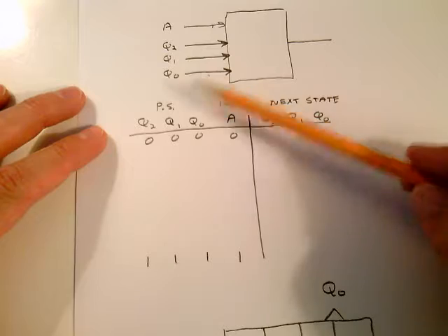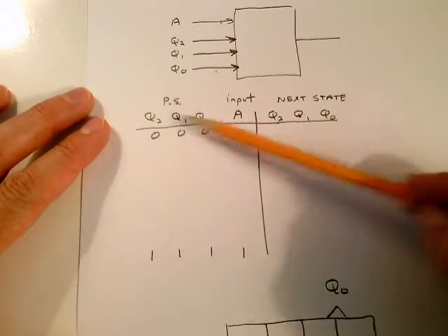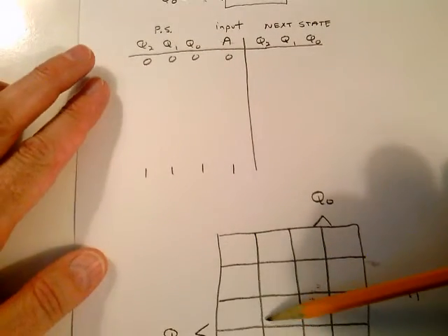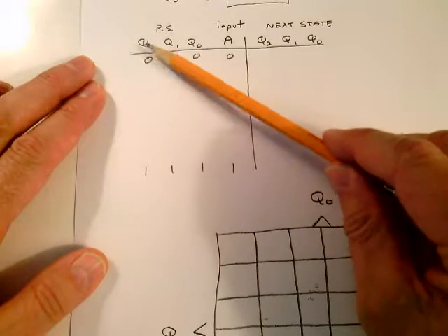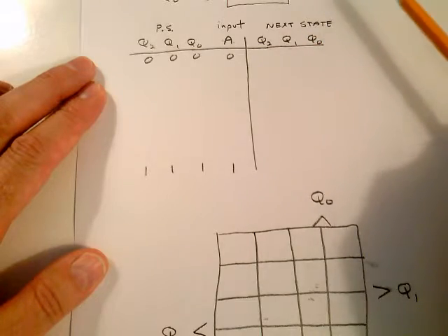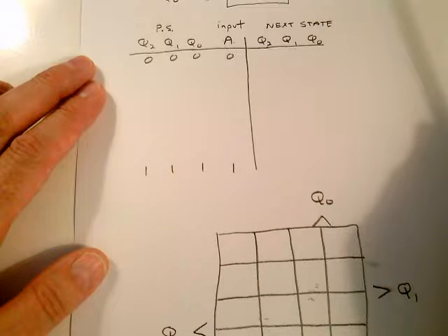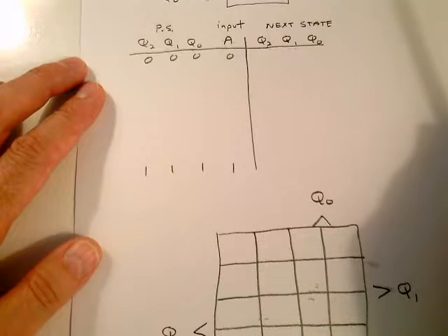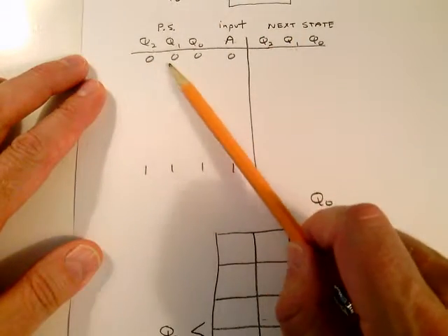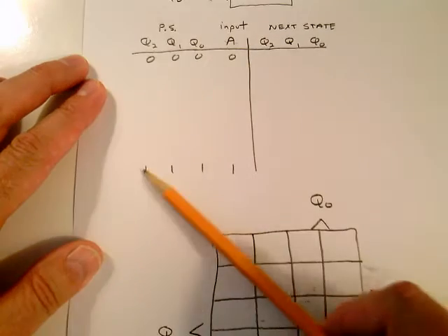But let's take a look at this. What I did in this case is just to do something different. I put the present states first, and I put the inputs second. Remember I said you could do that. It's just going to reflect down here. I put Q2, Q1, Q0 present state, Q2, Q1, Q0 next state. You fill all this out from your state transition diagram. I'm going to show you that in the next couple of designs. Pretty easy to do. These all go together as inputs. There's 4 inputs. You label 0, 0, 0, 0 to 1, 1, 1, 1.